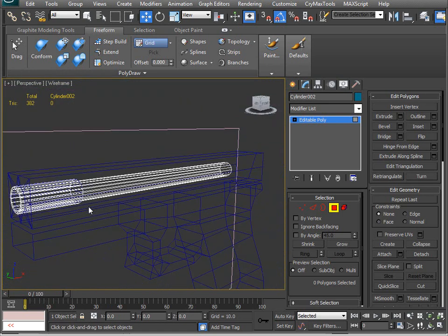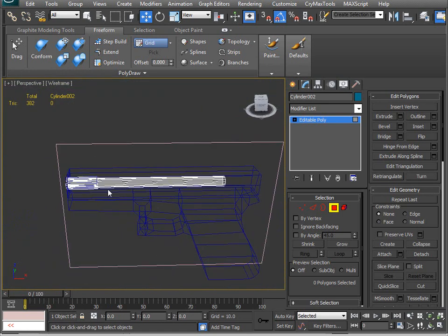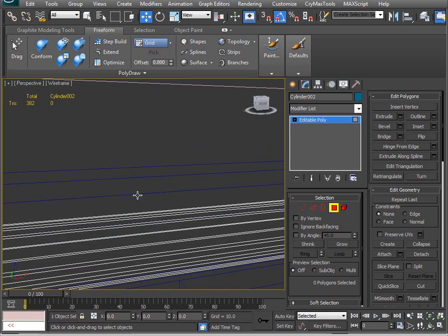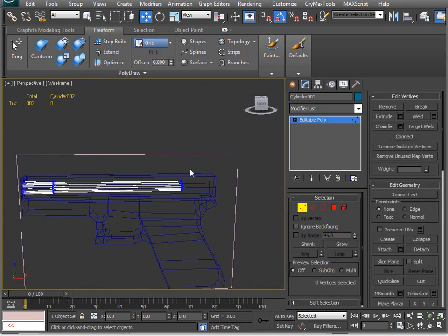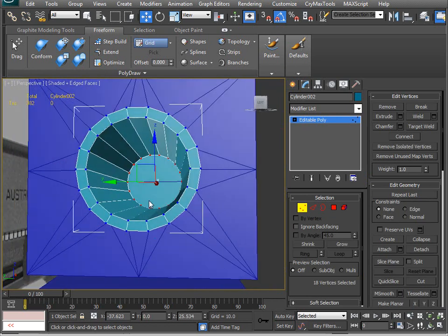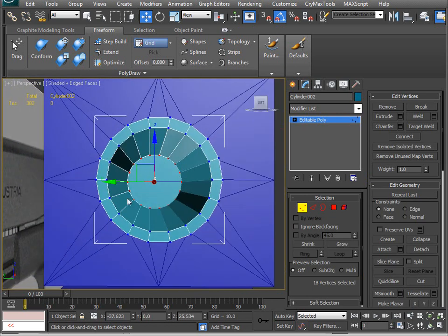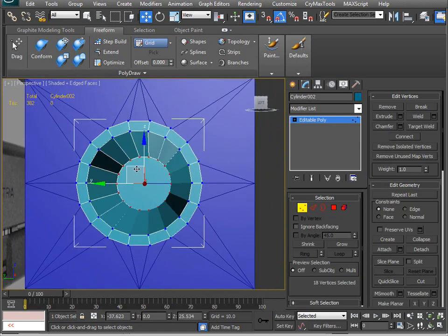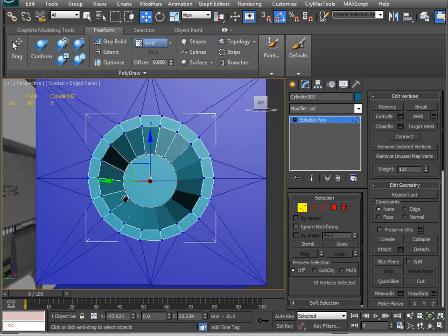I end up with a lot of texture space in here that's really just black solid color, so it doesn't do me any good to go that far back. All I gotta do in reality is go to about right here, and then when I go to map this with the textures, paint this black and also make sure that the specular value there is black, and it will look like a void.